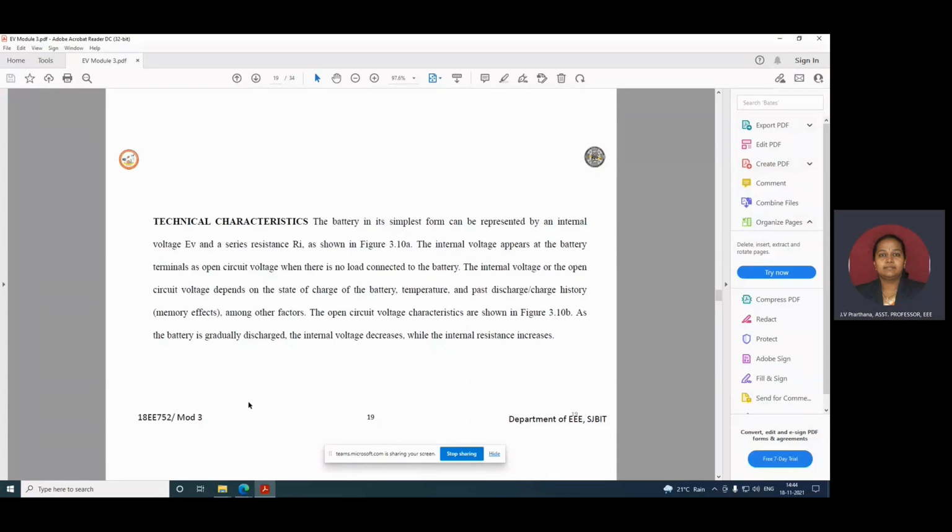Charge efficiency. An ideal battery would return the entire charge put into it, in which case the ampere hour efficiency is 100%. However, no battery does; its charging efficiency is less than 100%. The precise value will vary with different types of battery, temperature and rate of charge. It will also vary with state of charge.